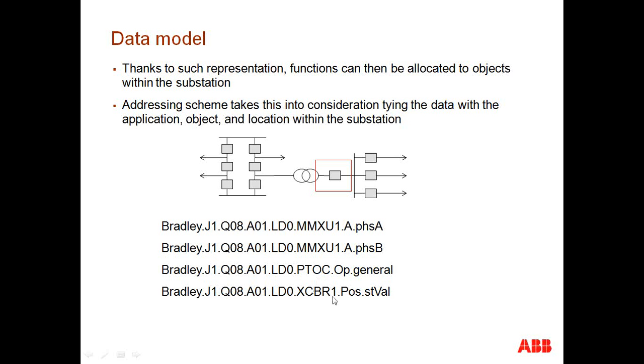for our breaker. So the key here is now we have a comprehensive and thorough addressing convention, where we can now assign logical nodes to locations within the substation. So what this does, from an integration perspective, is we don't really need an Excel spreadsheet or some sort of reference document that somehow the integrator or the end user has to keep track of, for this DNP or this Modbus piece of information and its association with the application and its location within the substation. It's all done within the addressing scheme of 61850.